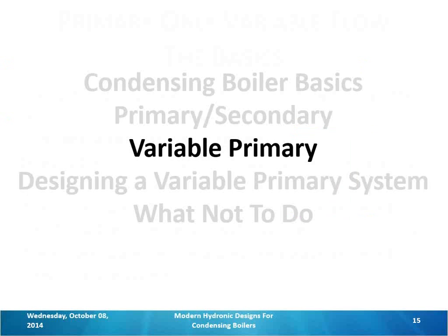We eliminate the boiler pumps. We eliminate the closely spaced T's and the buffer tanks, the hydraulic separation. We get a direct return back to the boiler and direct supply out to the system. We can get rid of the heat injection loops and all those other components.